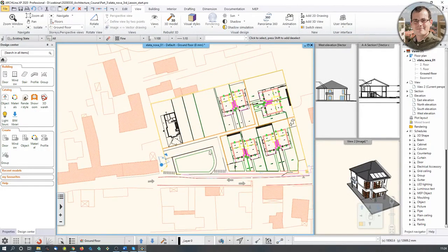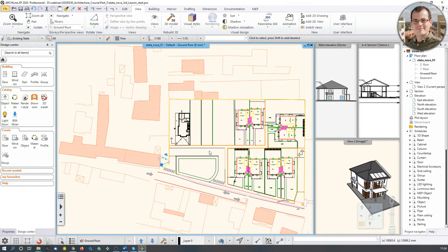Let's see what happens if I use this hotkey. Ctrl-Shift-R toggles the floor plan back and forth. So that way you can have multiple views of the same floor plan actually. And if you want to make it more convenient to work on, then that's how you can do that. So, very important distinction: Project North can be arbitrary, and True North is the one which actually influences your geolocation and shadows.